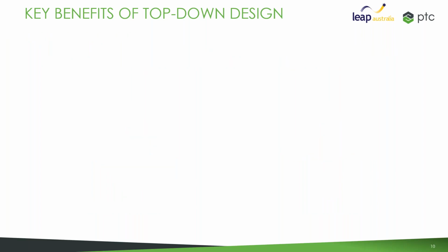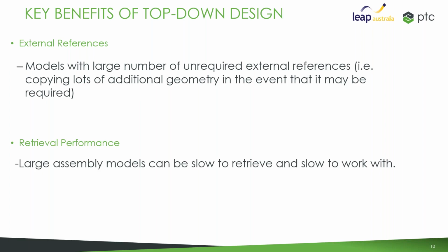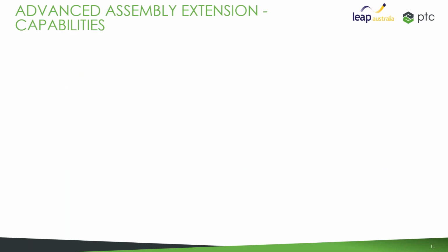If you have unnecessary external references, managing dependencies will be a challenge, and in most cases, ended up creating circular references. Also here, I would like to emphasize the benefits of top-down with the PDM systems, things like unnecessary checkout, issues with the migrations and handling of ghost issues and etc. And complex interdependencies will lead to spaghetti references, which will affect the performance and traceability and reuse of the large assembly.